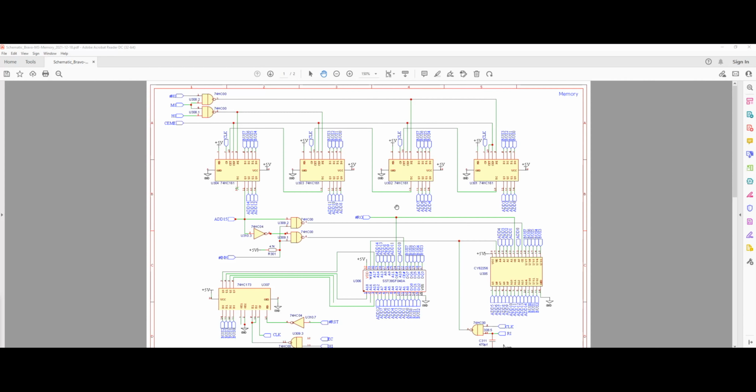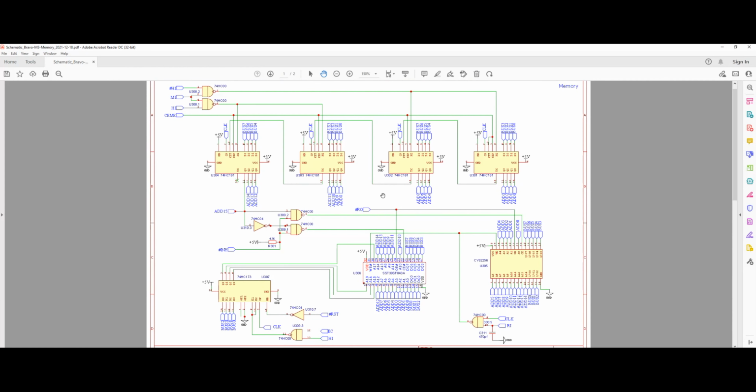Now, on the output side, there is a difference between here and what we had in our program counter circuit. In the program counter circuit, we actually had 8-bit outputs. So even on the output side, we had a concept of MSB and LSB, and the output was happening in 2 clock cycles. However, here, since we need a total 16-bit output, because we will be addressing our memories, and those memories require 16 bits, we're going to output everything at once in 1 clock.